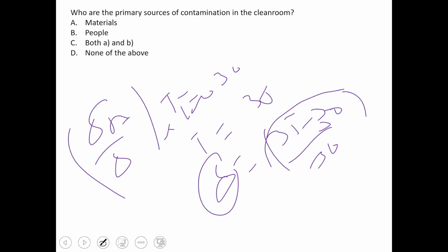So you have to wear the apron, a head cap on your head, and gloves when you enter the clean room. You have to pull out your shoes and socks, and wear the slippers they have already put in the clean room. You have to wear the slipper, mask, and in your foot, and there should be an air blower.